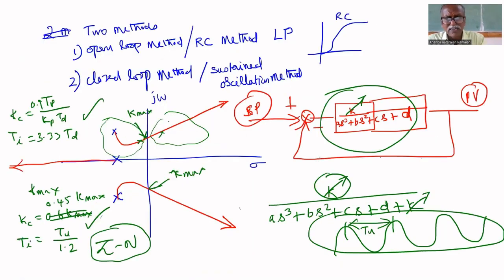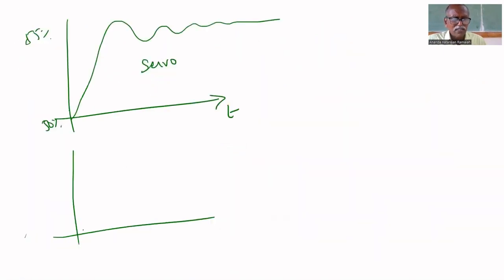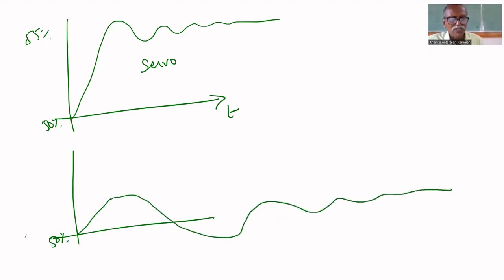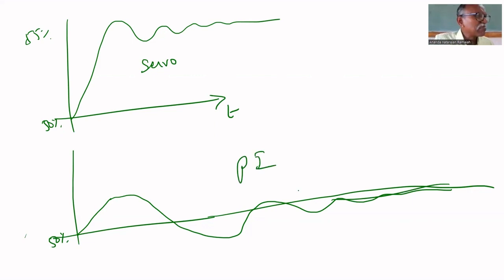If you introduce that disturbance here, what will happen? Suppose you are opening more, the flow rate will increase from 50% initially. It increases. That's why the controller takes necessary action and controls it again to 50%. Again, since it is a PI controller, it will settle. You can check for a P controller whether it works or not here. If you deliberately put a P-only controller and give some set point, definitely now it will settle.